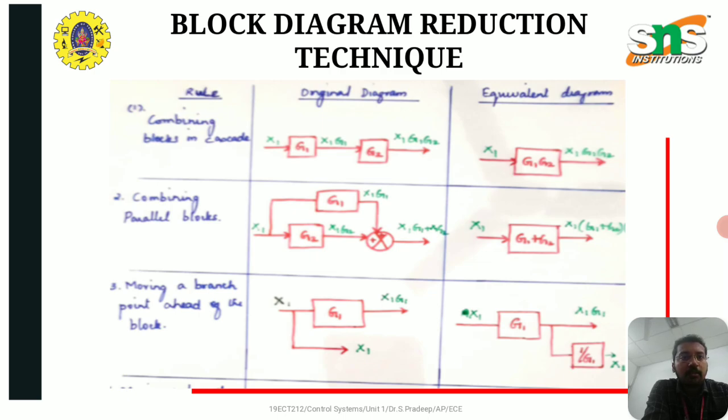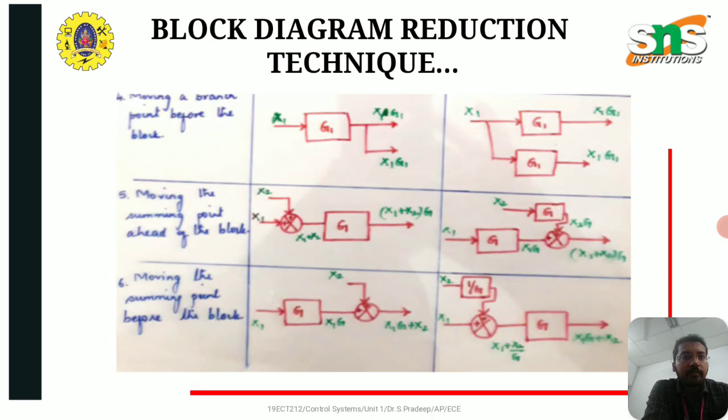The third rule is moving a branch point ahead of the block. While moving a branch point ahead of the block, the transfer function 1 by G1 is added. Moving a branch point before the block, G1 is added in addition to the transfer function G1. If we are moving the summing point ahead of the block, we again add a transfer function G. While moving the summing point before the block, we add 1 by G1 in addition to that G.